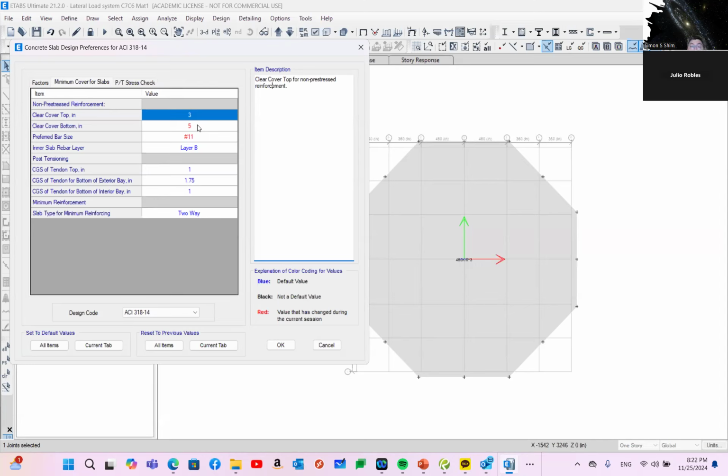It's based upon the bottom face of the concrete to the centroid of the rebar. So you may have to finalize it based upon your final design decision, right? So which rebar do you want to put in next, inner versus outer layer?